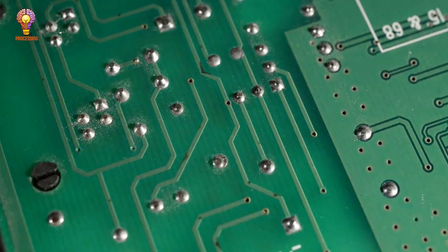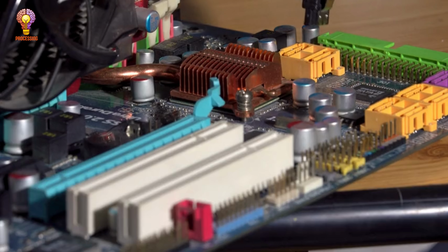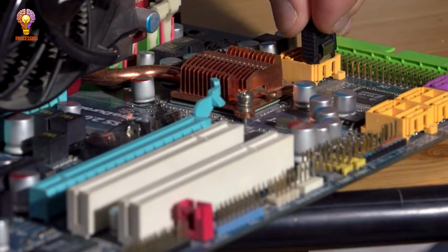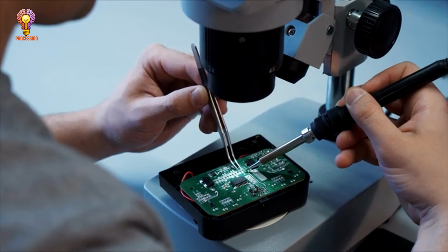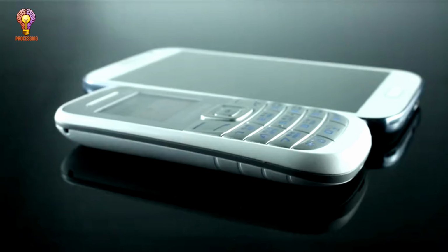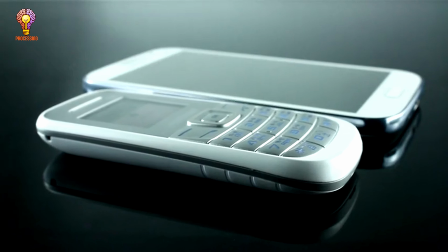3. PCB (printed circuit board) assembly. The motherboard is assembled, with processors, RAM, and other components mounted onto it using automated robotic systems and surface mount technology (SMT). Soldering is performed to connect components, followed by automated optical inspection. 4. Phone body and frame production. Metal or plastic frames are molded, CNC machined, and undergo polishing, painting, or anodization for durability and aesthetics.